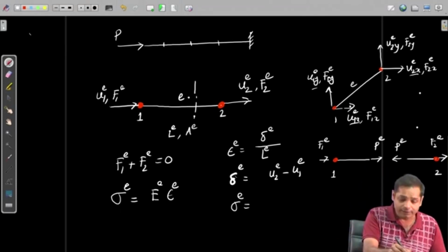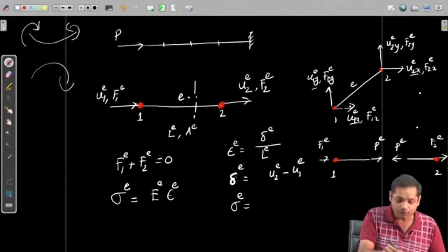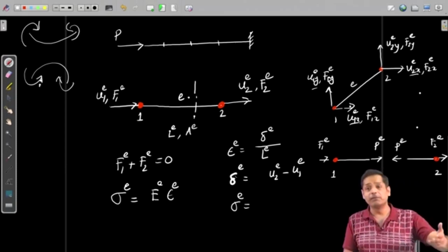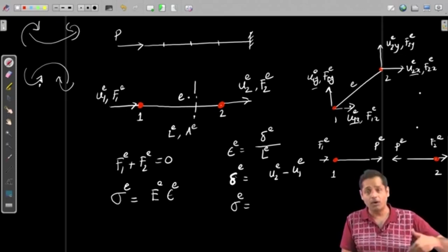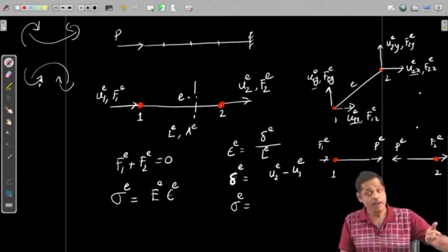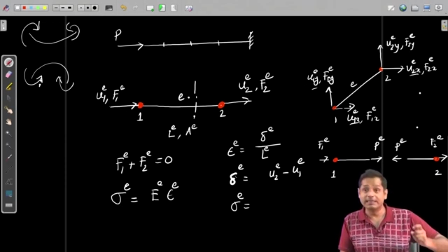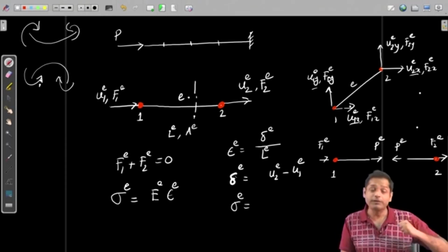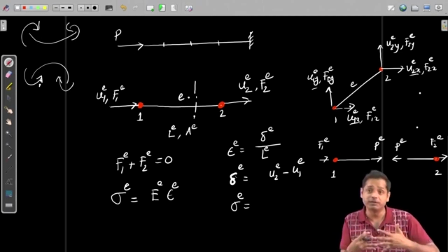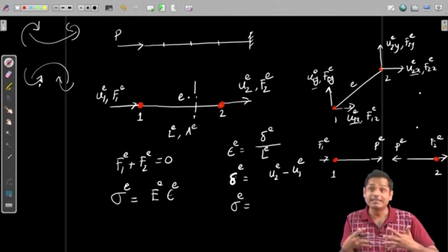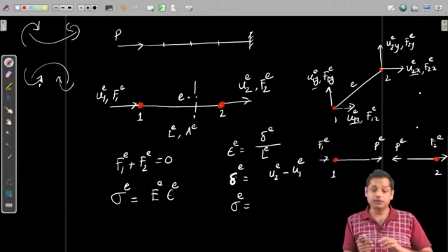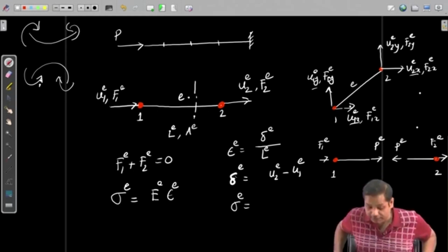During bending, if it is bent like this, we call it a sagging moment. If it is bent like this, these are hogging moments. The general convention is that a sagging moment is considered a positive moment and a hogging moment is considered a negative moment. But this positive and negative is just to understand the nature of the moment. When we do algebraic manipulation between moments, the addition and subtraction should be based on whether it is clockwise or anti-clockwise.